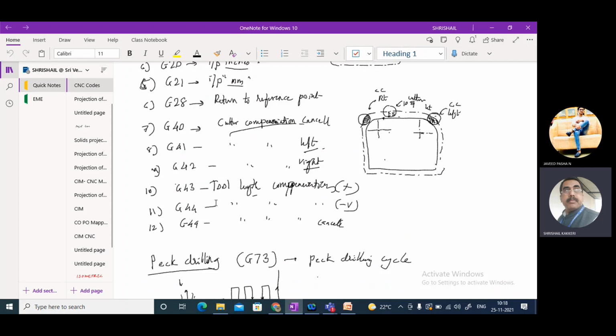Whether it is plus or minus, I don't want to confuse you here. Now, after using for 10 holes, the tool length has decreased by 0.5 mm. It is not observable, I am just giving you an example. Now, what happens? If I use 25, it will go only 24.5 mm because the tool length has been reduced. Correct? So it will not happen, because online inspection sensors will be provided.